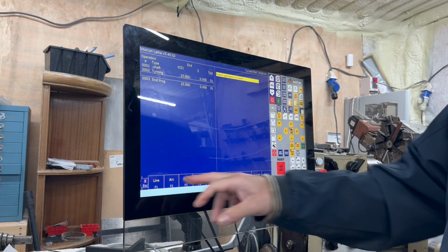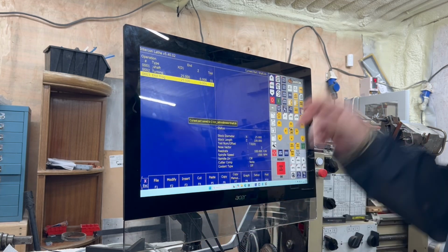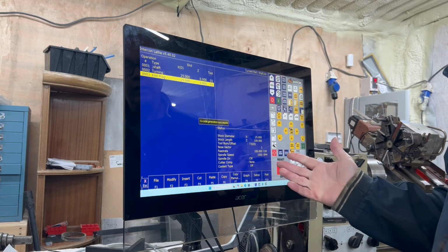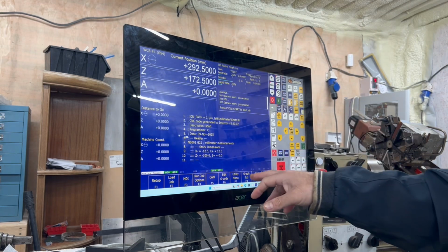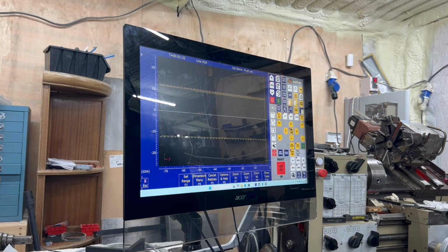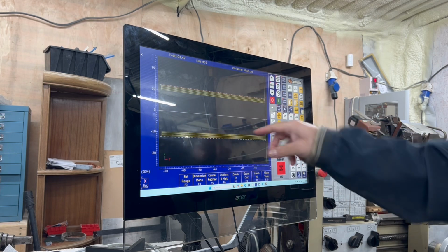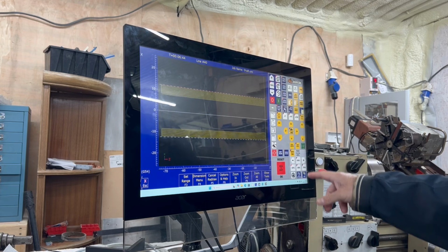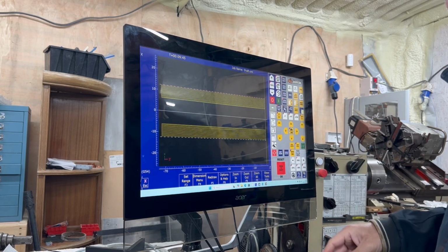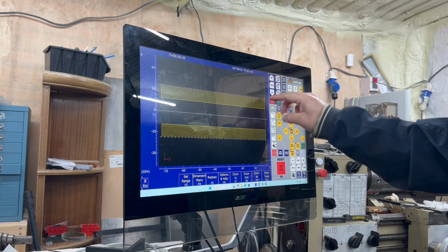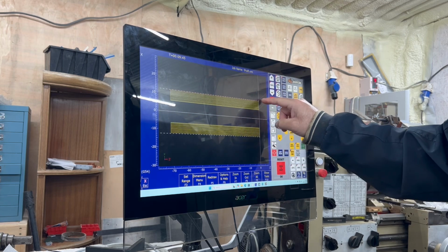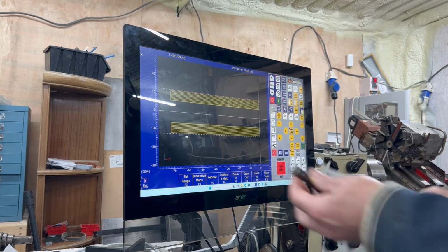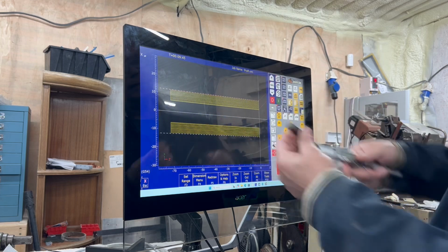Now if you go to escape there and you press post, unless there's an issue, it'll tell you the code is fine. Now graph job will show me exactly what it's going to do. So you can see, and the reason it's showing it slowly is because I've actually got rapid and feed rate overridden from some earlier testing I've done. There you go, starts there. We'll do these. So what we've now done is we've done that.